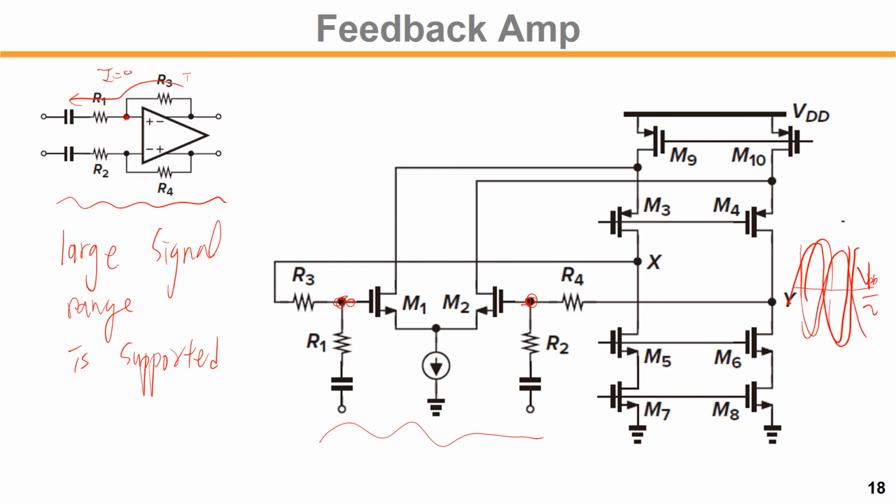We already showed what would be the limitation of the input common mode, so I'm not going to talk about it again. So half VDD input and output CM is well supported.